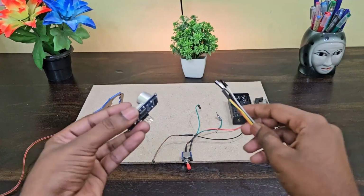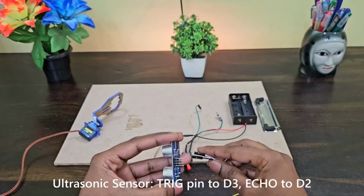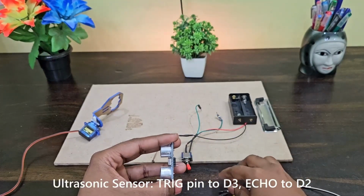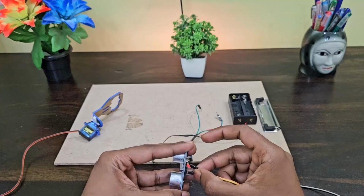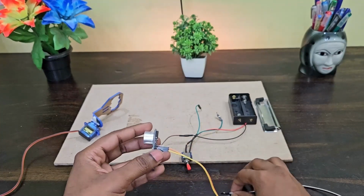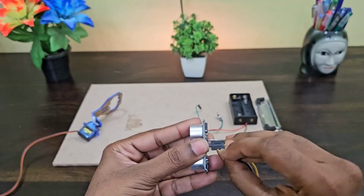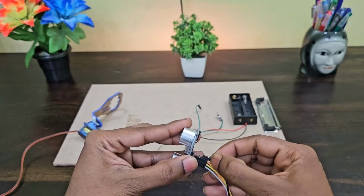Now that we have seen the components, let's wire them up and understand how they work together. First, we have the ultrasonic sensor. The trigger pin connects to D3 and the echo pin goes to the D2 pin. This sensor sends out ultrasonic pulses and listens for the echo signals, allowing the Arduino to calculate distance based on the time it takes for the signal to return.